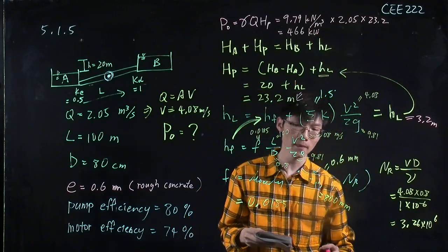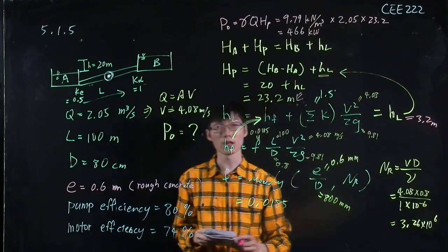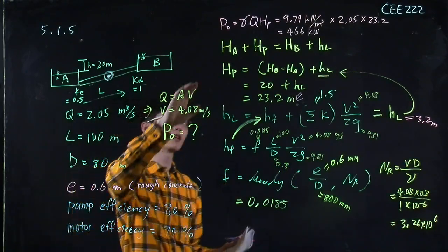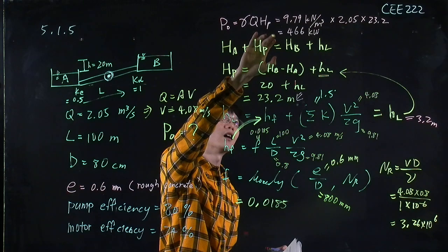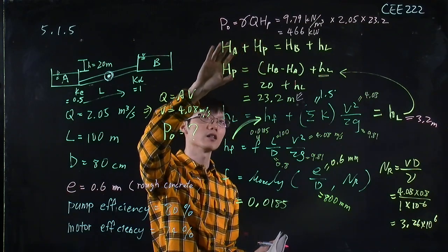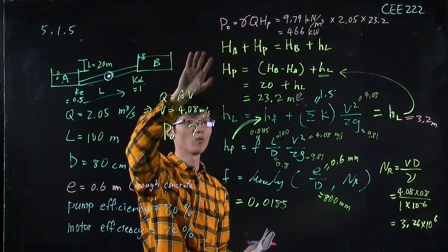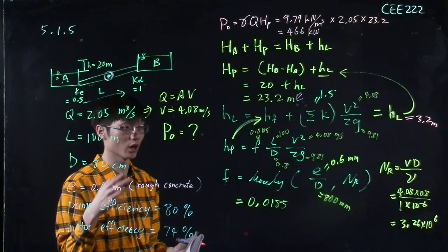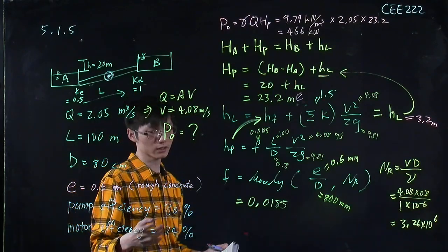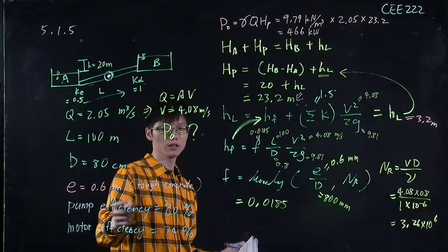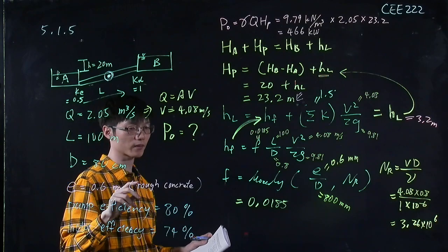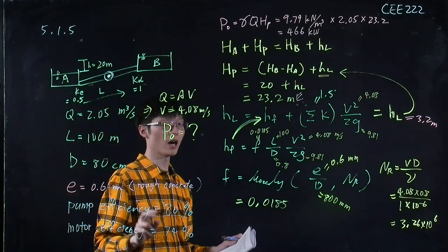Is this the end of the calculation? No, it's not, because this number is only true when the efficiency equals 100%. But from the problem, we know that neither the efficiency of the pump nor the motor equals 100%.